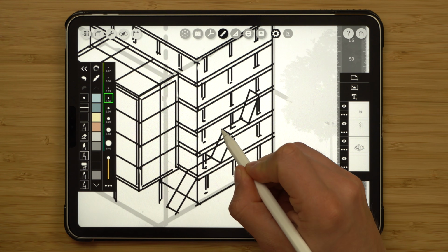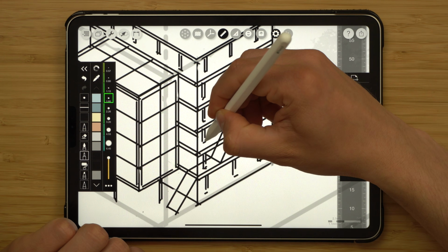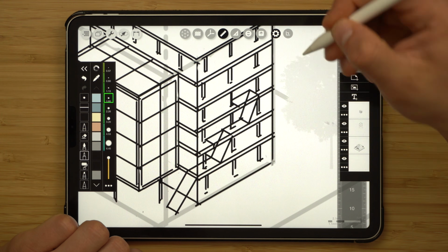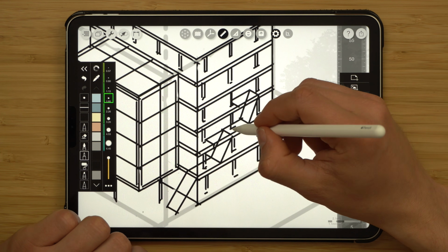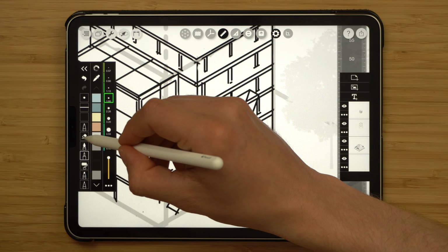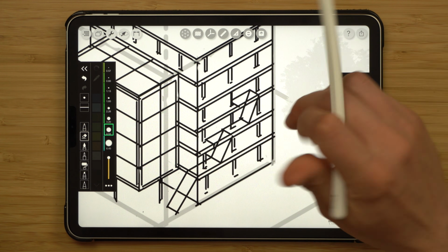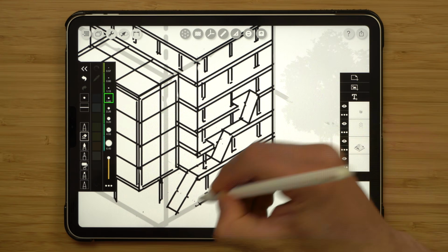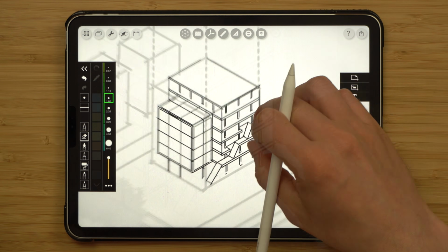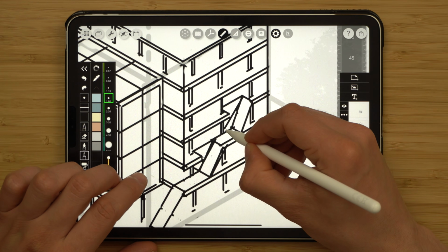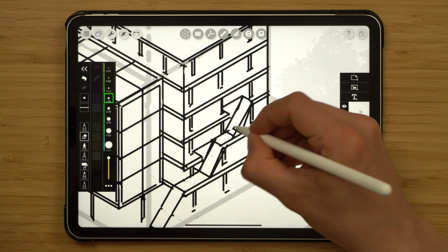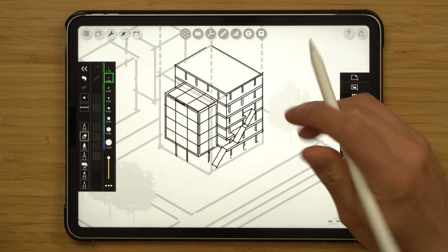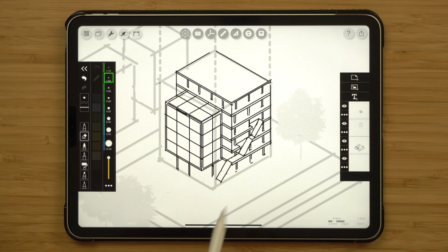I actually want, for the stair, a little opening in the slab, so this floor will have an opening to allow people to pass through, and the same on the floor above. And luckily, these openings in the floor coincide with where the free space between columns is, so that's quite good. Again, I'll enable the eraser, unconstrain, reduce the size of the brush, and then just delete the excess. Going to adjust the pitch of these stairs because they're not quite in line, and erase the excess once again. So hopefully now these stairs make a little bit more sense. Pitch of the flights is the same.